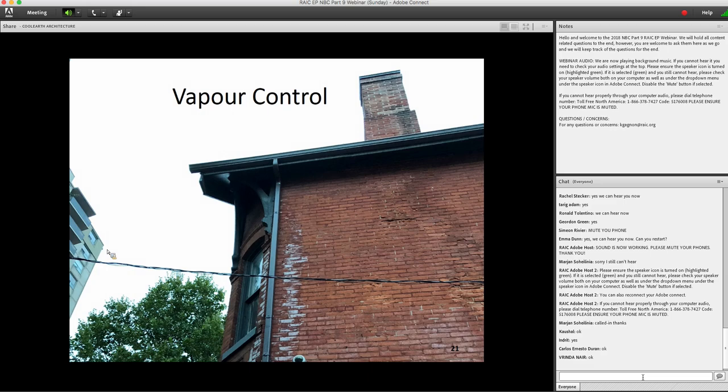But what we see here is white efflorescence on the materials, and what it shows is that now that the downspout is fixed, the water that was absorbed by the brick, by capillary action or by penetrations, maybe there were holes there, started to dry out again through vapor diffusion.